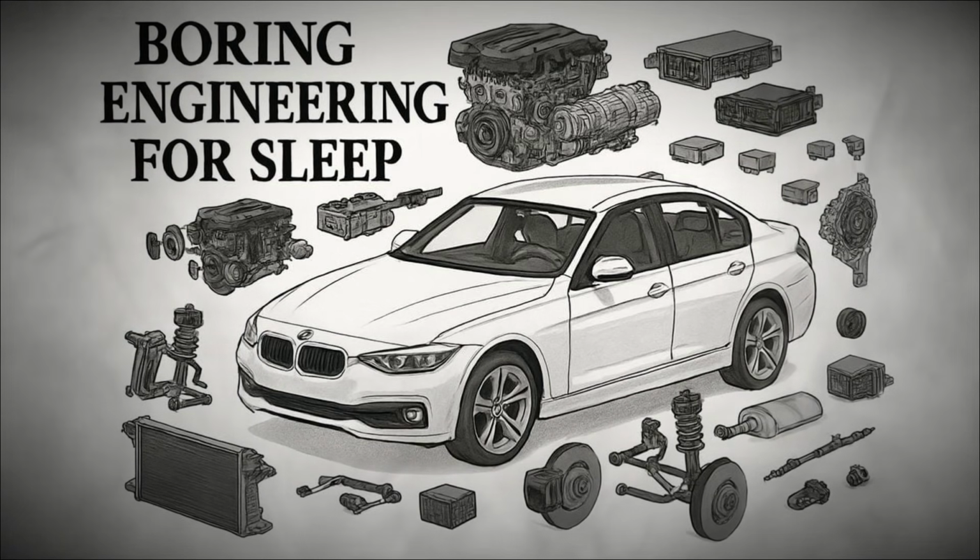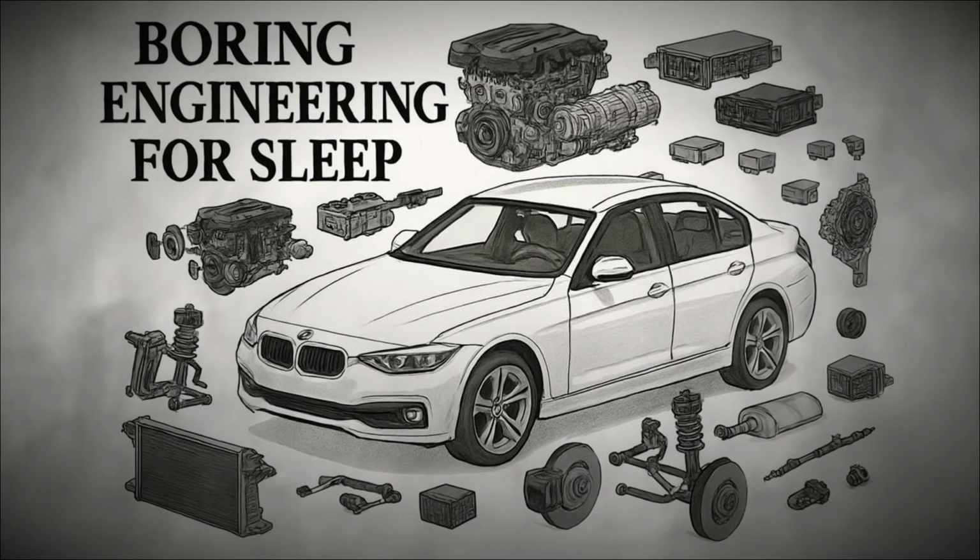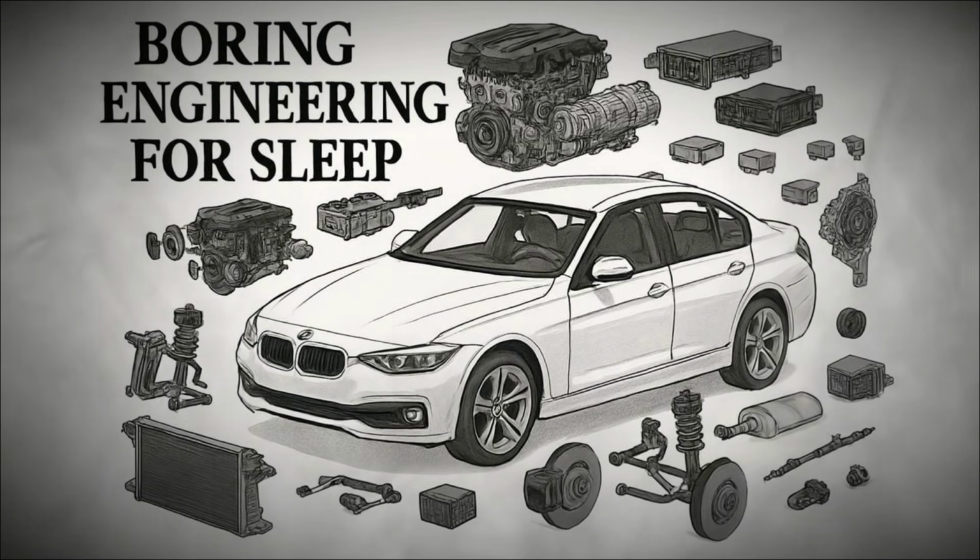Sensors are the foundation of electronic integration, and they measure everything from wheel speed and throttle position to cabin temperature, ambient light, and even driver attention. Cameras, radar, and ultrasonic sensors provide information for advanced driver assistance systems such as lane keeping, adaptive cruise control, and automatic emergency braking.